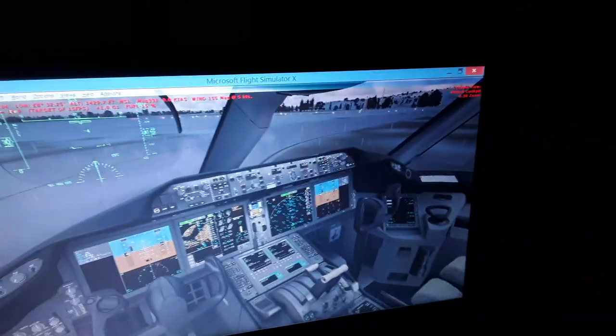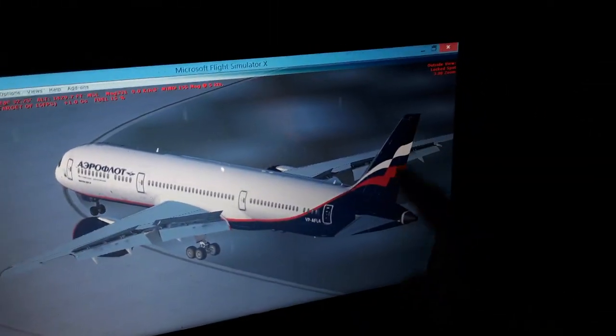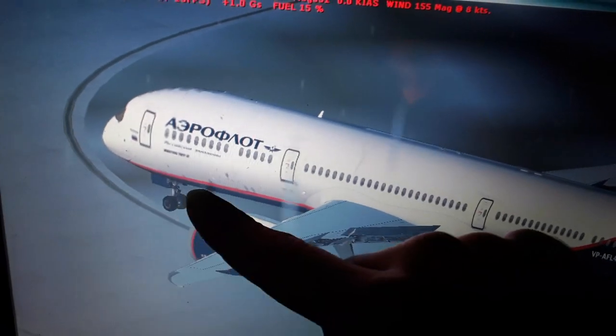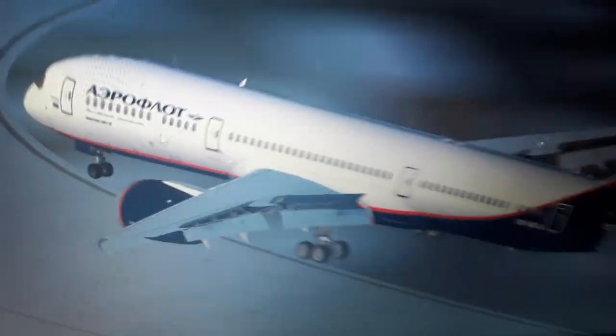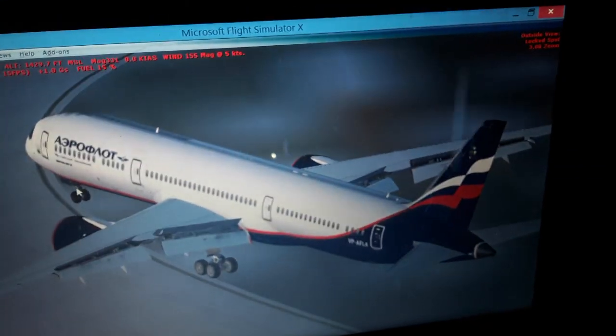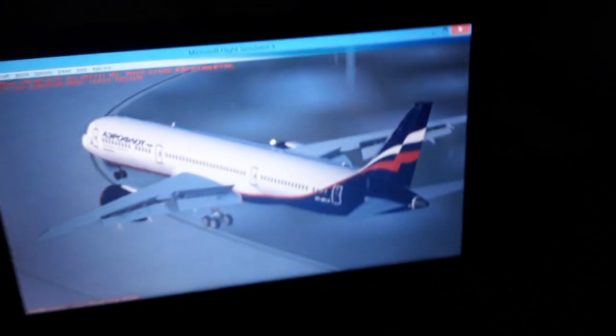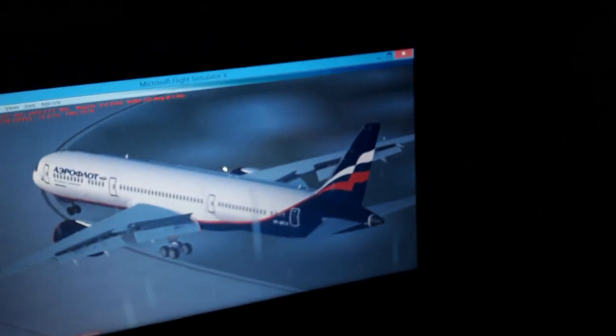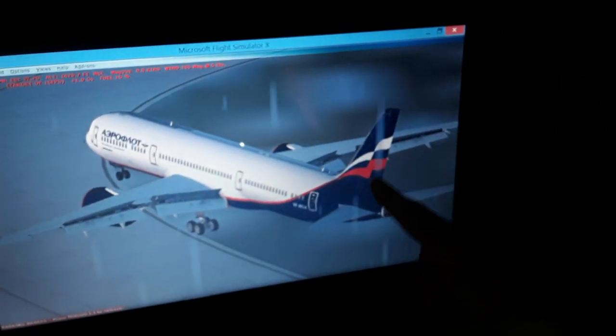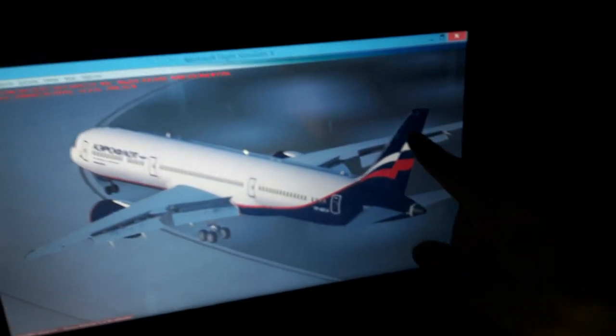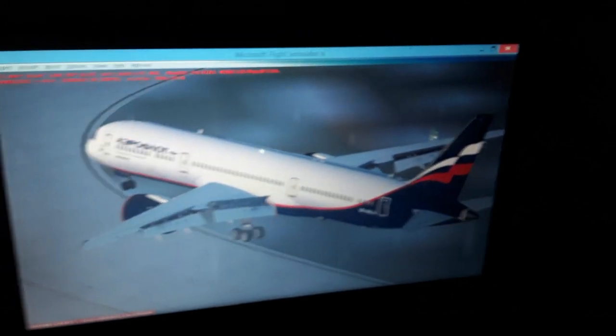So as we accelerate for takeoff above 80 knots or 144 kilometers an hour, the forward nozzle is locked to 0 position, 0 deflection, from the computer automatically. We don't need to do anything in either case. It is automatic from the computer, and we have only the rudder aerodynamically effective above 144 kilometers an hour or 80 nautical miles per hour over here in takeoff.